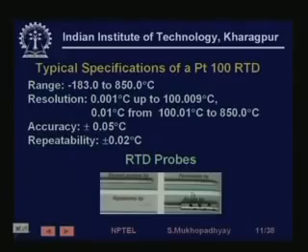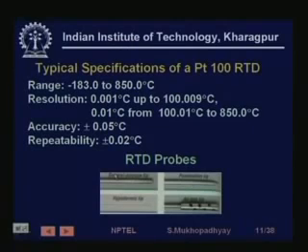So you put the probe, and outside you put another cylinder with some holes, such that the fluid inside, whose temperature is actually sensed, is not so much affected by the flowing fluid. That's why you have this kind of probe for air or gas. Sometimes you like to penetrate the probe into something and measure the temperature inside, or you could have a general purpose tip which is just fixed to the medium.